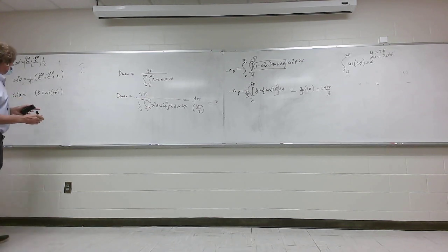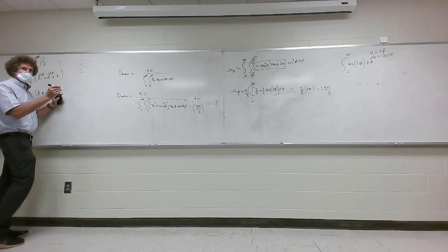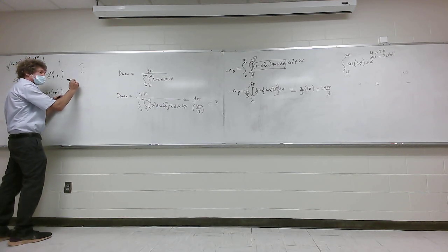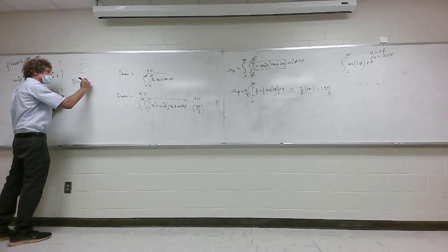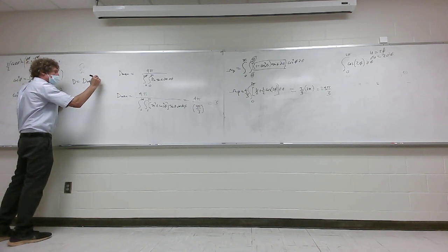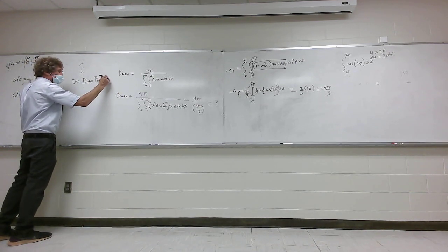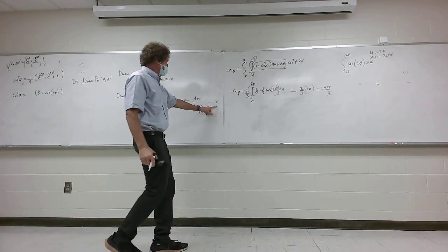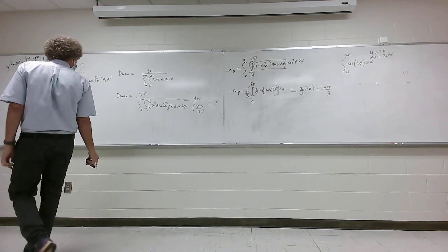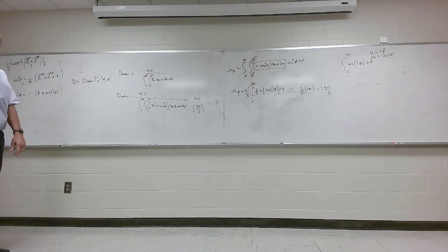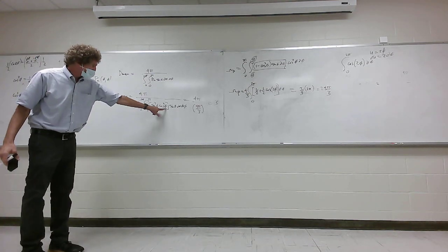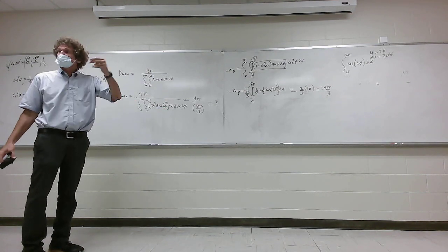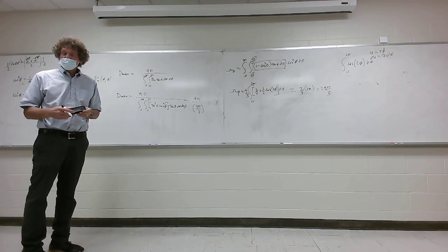Okay, so that's 3, but that doesn't quite answer the question of the directivity for all angles. The actual function for directivity will be D max times the normalized power density, which is the function of theta and phi. So you take this D max, which is 3 that you calculated, and then you multiply by that normalized power density, which is this expression. Okay, class? And that's how you get the directivity in general for all angles. Y'all with me?